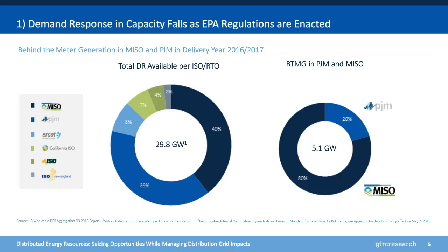And when we look at distributed energy resources traditionally, market interaction has largely been driven through these demand response programs at the ISO level, where a significant amount of those resources have actually been behind-the-meter generation. As we move forward within the wholesale markets, we're seeing increasing interest from many other types of distributed resources that have traditionally not interacted with markets, such as distributed solar or energy storage, and integrating into some of these traditional programs as they change to adapt to a more distributed electrical system.